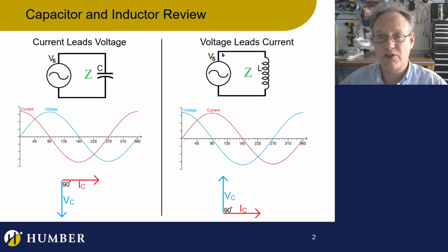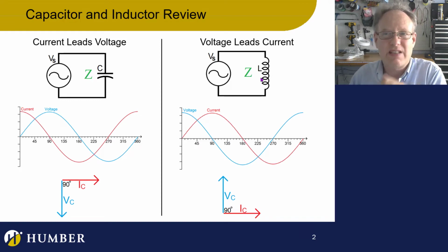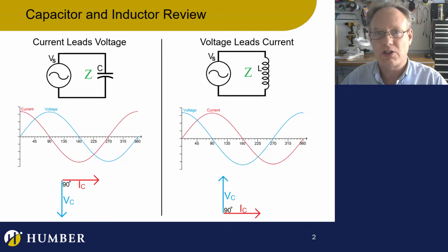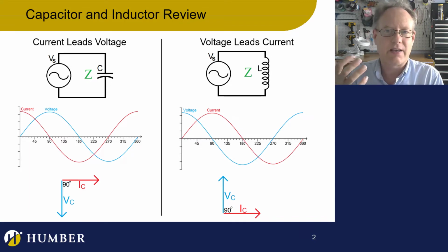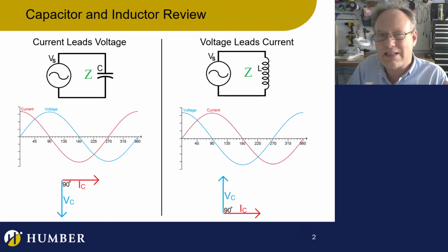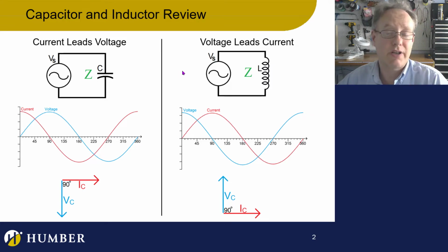Over here, as soon as we power this up and any kind of current goes through the inductor, it produces back EMF and its resistance goes up. That resistance slows the current down. The current is slow at first, but the voltage drop across the inductor is really high because it acts like it has really high resistance, or resists the current really strongly. That's because of the back EMF. If you want to know a little more about how that works, go back to last week's lecture on RL circuits. Okay, good.